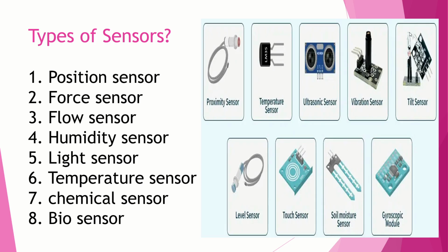Occupancy sensor detects the presence of people and animals in an area, while motion sensors also detect people and objects. The difference between the two is that occupancy sensors generate a signal even when a person is stationary, whereas motion sensors do not. For example, electric eye.